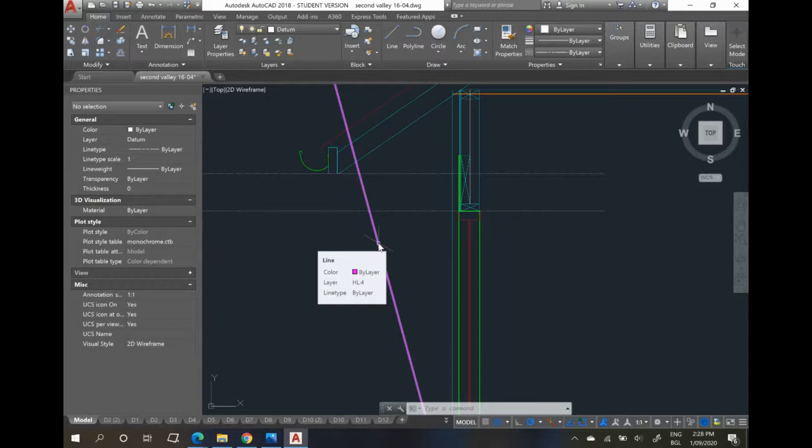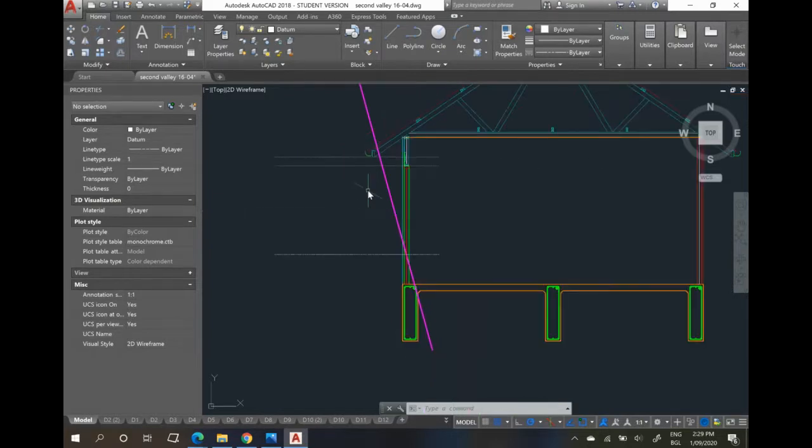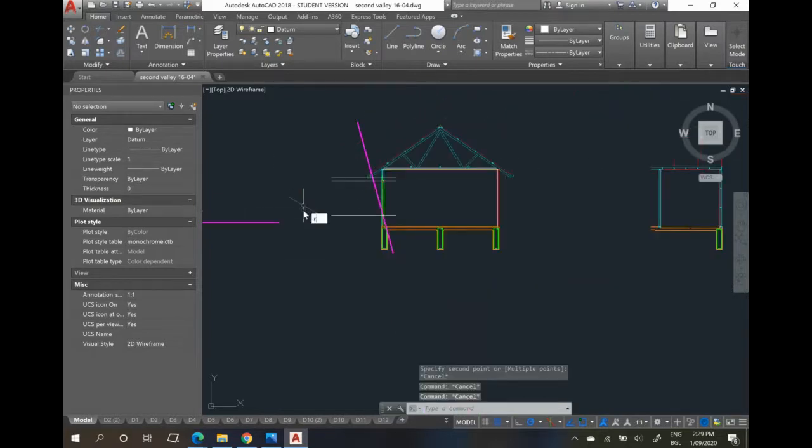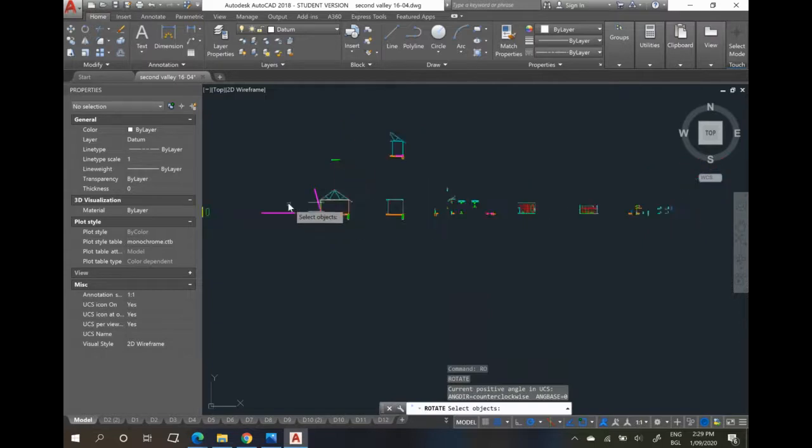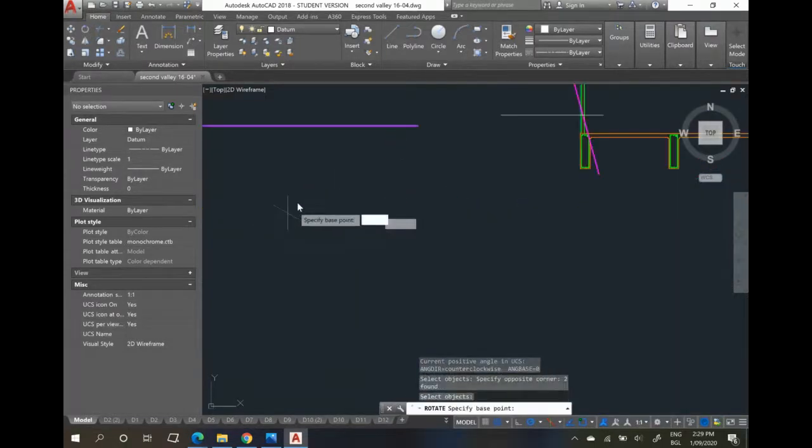So it's close to midday. I can call it May roughly. So at midday summer solstice, that's our angle of sun. So let's say we were to set our eaves at that. Now I won't go mucking around with this drawing and setting our eaves, but what we'd basically do is move that and bring it over to here to chop our eaves back to 462. Then we've also gotten our angle for winter sun.